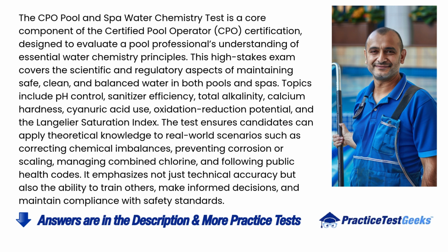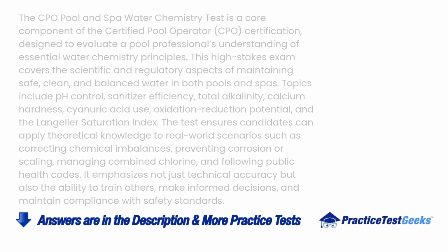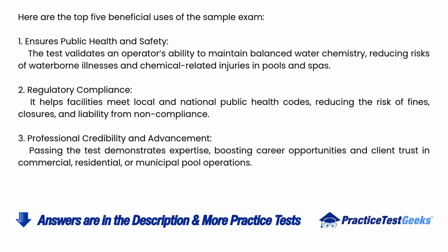spas. Topics include pH control, sanitizer efficiency, total alkalinity, calcium hardness, cyanuric acid use, oxidation reduction potential, and the Langelier saturation index. The test ensures candidates can apply theoretical knowledge to real-world scenarios such as correcting chemical imbalances, preventing corrosion or scaling, managing combined chlorine, and following public health codes. It emphasizes not just technical accuracy but also the ability to train others, make informed decisions, and maintain compliance with safety standards. Here are the top 5 beneficial uses of the sample exam.